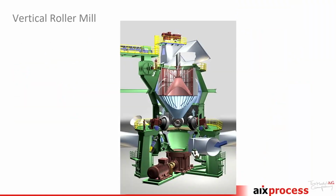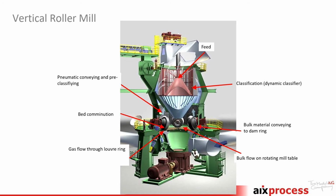If we are looking at a vertical roller mill, this is the typical design for a cement mill. You will see that it has a lot of features built in. It's one machine, but it's a whole branch of processes within the machine. So you have comminution at the bottom. You have pneumatic conveying of the cement towards a dynamic classifier. So you have internal recirculation. And you have a bed conveying here. So a lot of things are going on within these vertical roller mills.